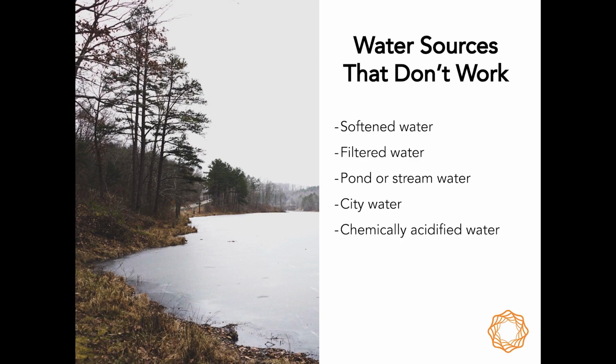And then lastly, it is not enough to acidify the water with added acids, such as sulfuric acid or phosphoric acid or acetic acid, etc. While those materials do help, they do have an impact, but they don't make nearly as big of an impact as reverse osmosis, and they just take the edge off the most severe part of the problem. So here's why. Let's say that for the sake of discussion, we have a water source that has been tested as having 500 parts per million of total hardness.